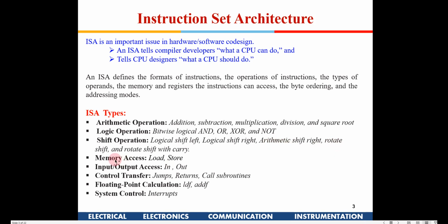Now rotate also. Rotate shift means, say if I say rotate left, all the bits will be moved toward the left, and whatever bit is coming out of the register from the left-hand side will be brought back to the right-hand side, into the least significant bit. Similarly, if I say rotate right, the bit which is coming out from the LSB will be fed back to the MSB.